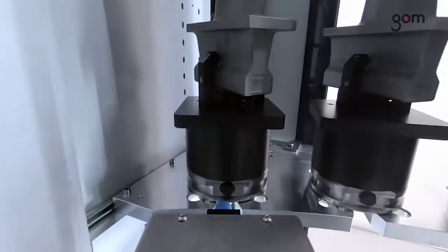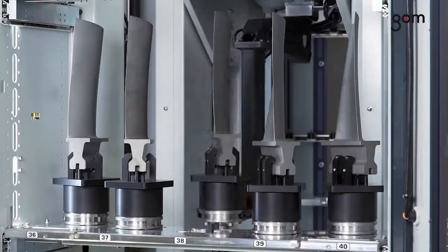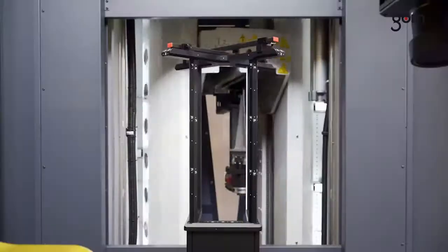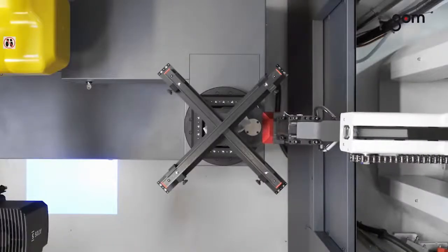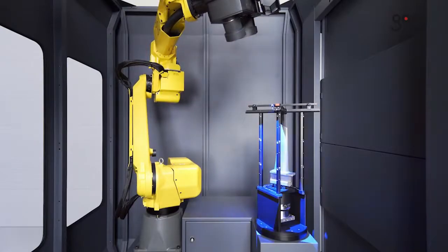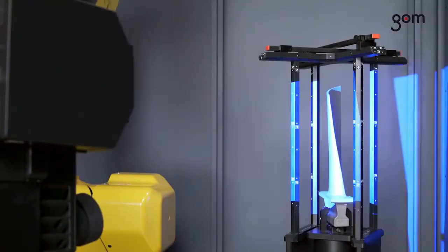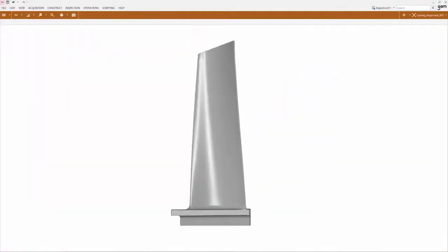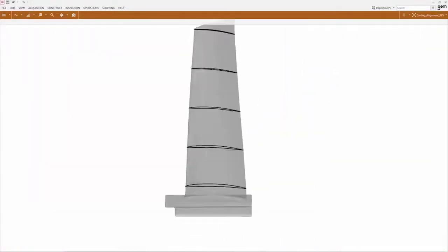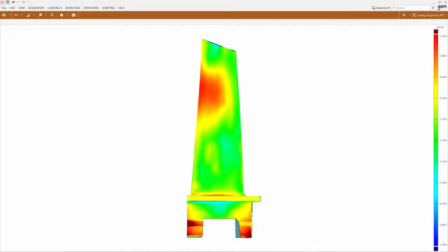Simply, an operator can pull a part from the manufacturing floor, let's say one every 10 or so runs from that machine, and this process is what we would call batch sampling. So how can this help us learn more about the manufacturing process? Well, after we take 5 individual batch samples and scan each of those parts with our ATOS scanners, we will then be able to have the measurement data for those 5 individual parts, or what we would commonly refer to in the software as stages.